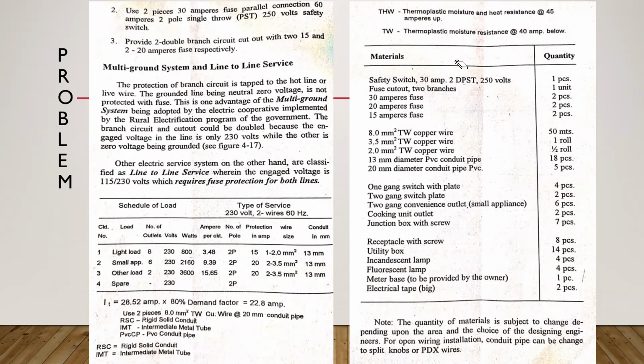So, kahit na yung ating voltage is 220 to 230, yung ating safety switch is meron siyang safety factor na kahit na mag-fluctuate larger than 230 yung ating voltage, is yung ating safety switch is safe pa rin kasi ang kanyang voltage na ina-anticipate is up to 250 volts.